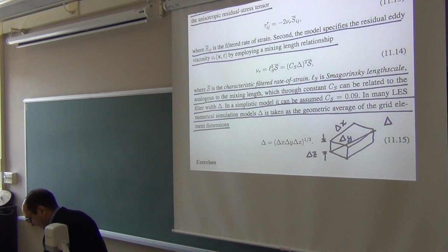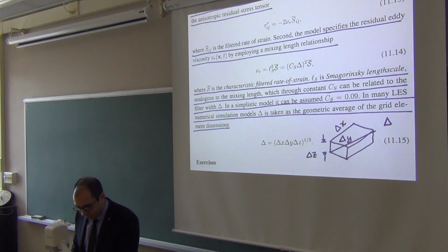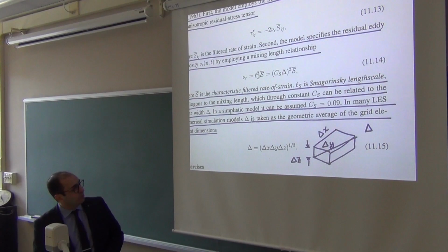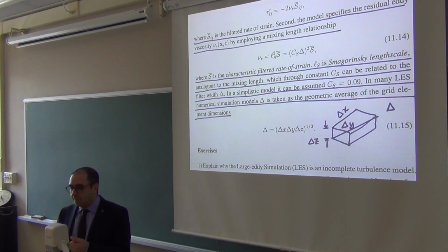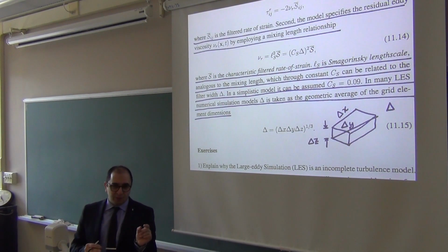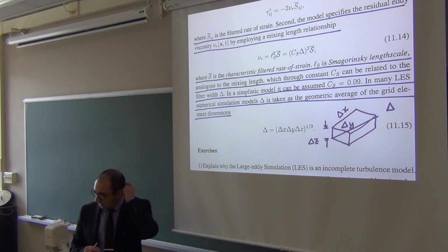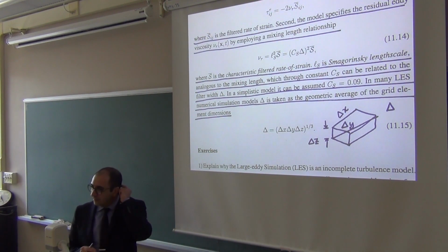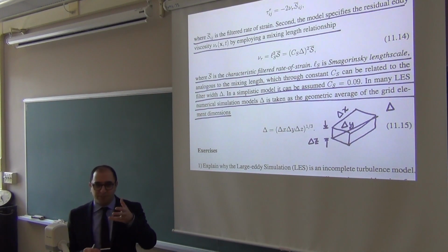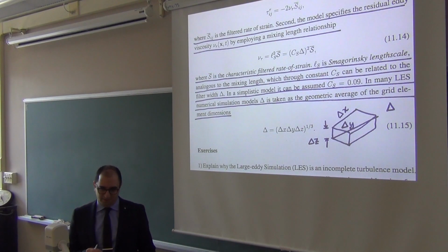Okay. I really don't have much more to say about LES. The equations are the same, the solvers you use for them are the same, but they're just transient, and you just treat larger scales and smaller scales differently. You actually solve the equations as a transient flow. It's the same Navier-Stokes equation, nothing is different. You just solve it in transient mode, and you obtain a time-varying solution. But you are aware that the smaller scale is being modeled, not being resolved. Okay, so it's always a transient simulation.